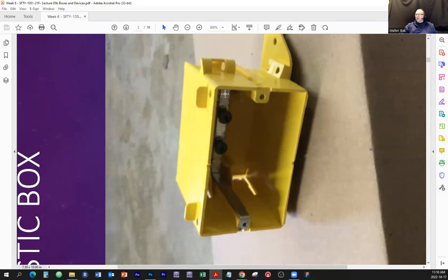So in order to still have a bonding terminal, we have here the bonding terminal that extends to one of the screw terminals. Why do we have that? Well, we still have to have the bonding terminal if we are doing a regular installation. For example, some of the devices such as a duplex receptacle would have a bonding screw terminal, so you still have to connect it to something.